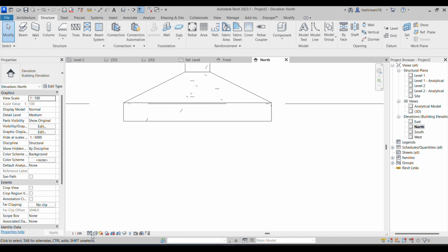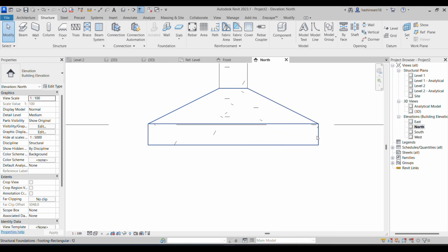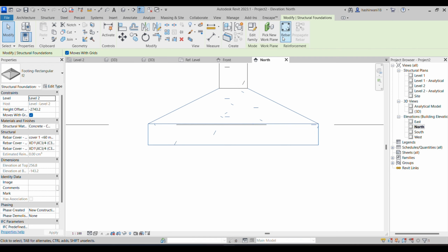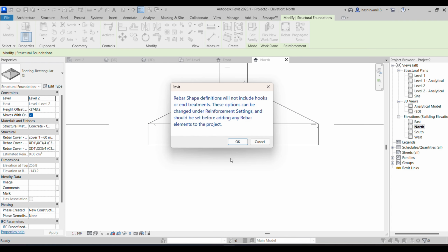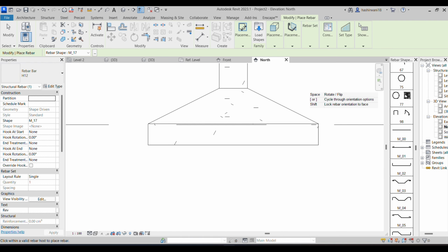What I'm going to be doing is I'll just go here and go to the wireframe, and then I'll be selecting this, and we have an option here called Rebars. Can you see the option here called Rebars? I'll select this, a dialog box appears, and then I'll click OK here, and a different window appears. We have different sorts of Rebars that have appeared.